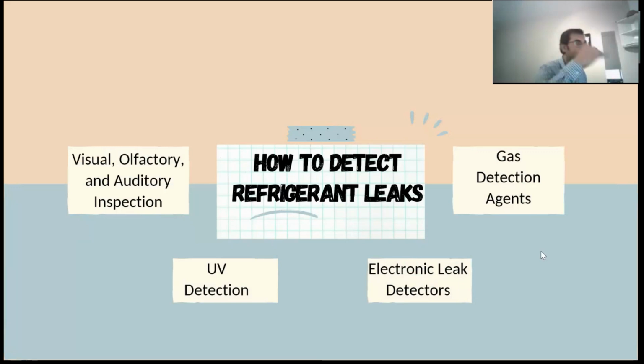In case of flammable refrigerants, they are flammable up to a certain level, meaning their flammability temperature is high. But if there is a leakage, there can be an explosion. So in those cases, leak detection is absolutely mandatory. Sensors or systems are required, or drains should be connected with a sensor so that the flammable refrigerant can be drained out to a safe, dedicated place where there is no chance of explosion.